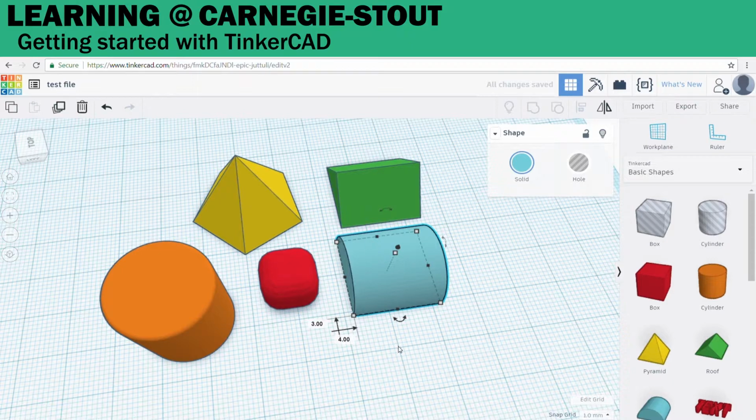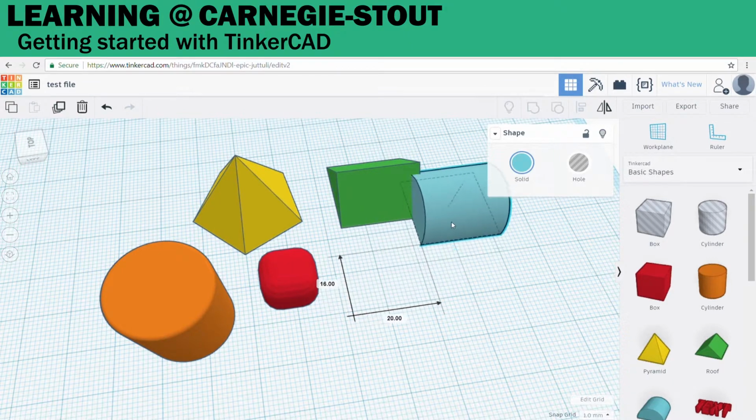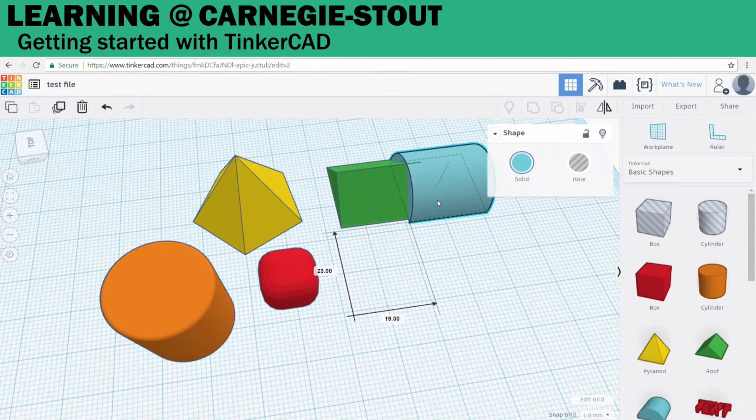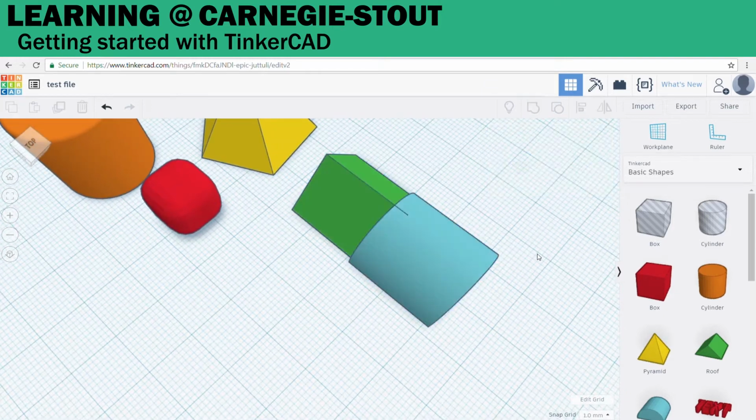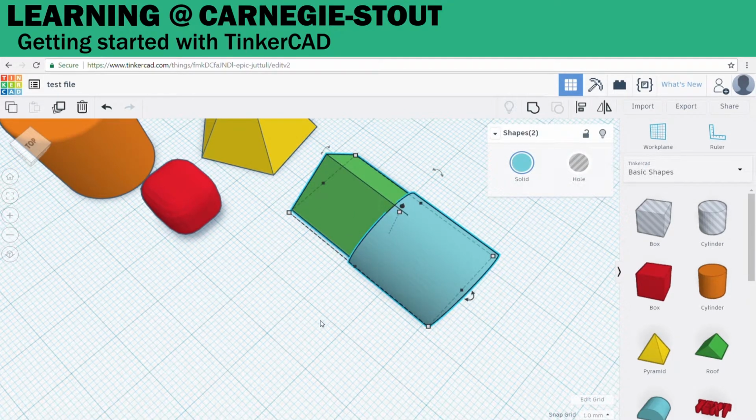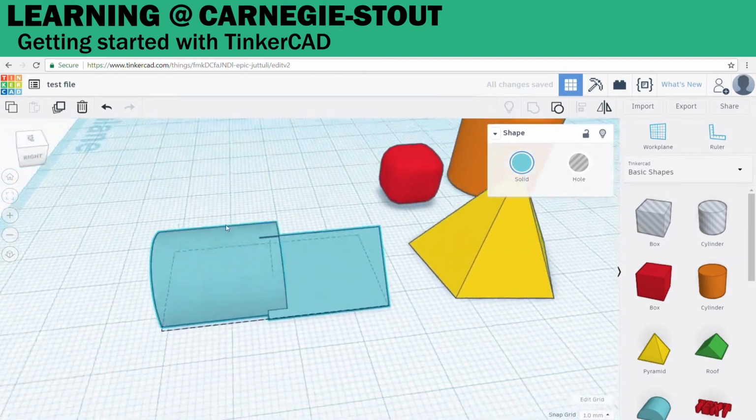You can combine multiple models together to create complex shapes. Position your models where you would like them to be by clicking and dragging, and then select more than one at a time. You can do this by either left-clicking and drawing a selection box around multiple shapes, or hold down the Shift button and left-click to select multiple shapes. When you have more than one shape selected, the group option appears. Grouping two shapes together makes them one solid shape.